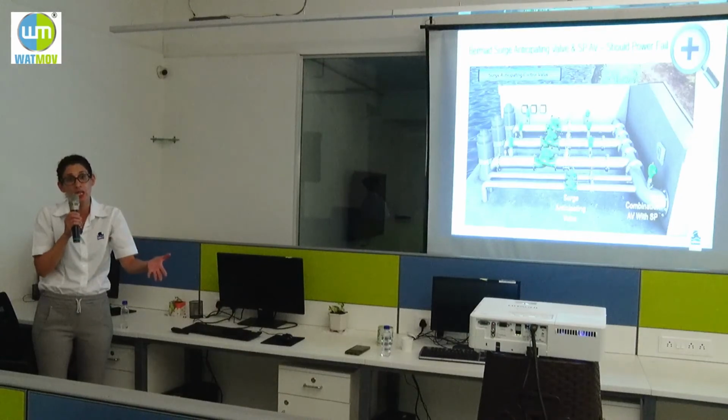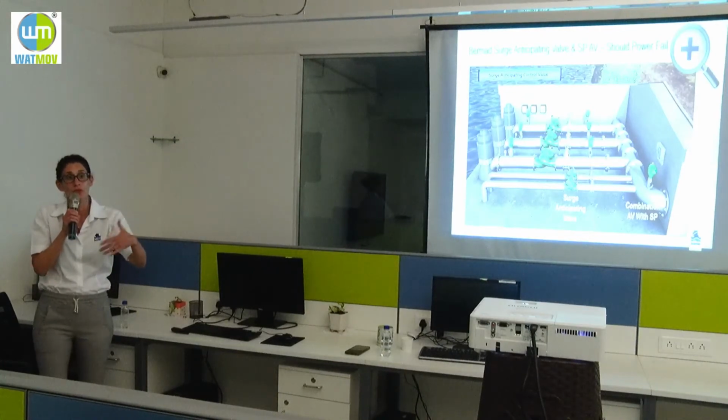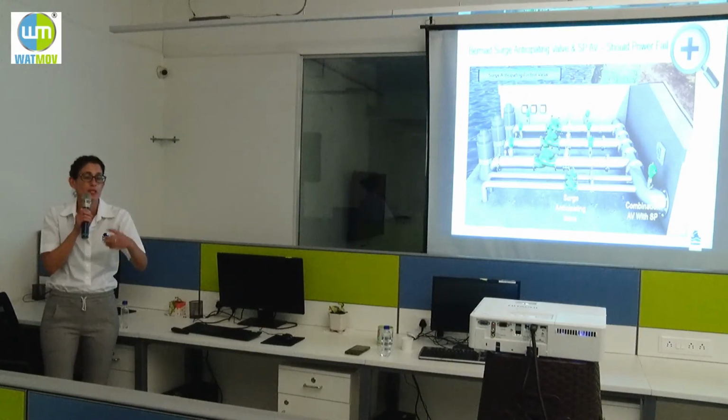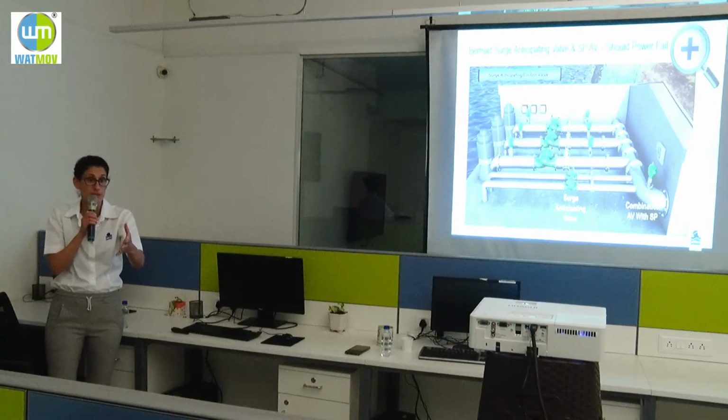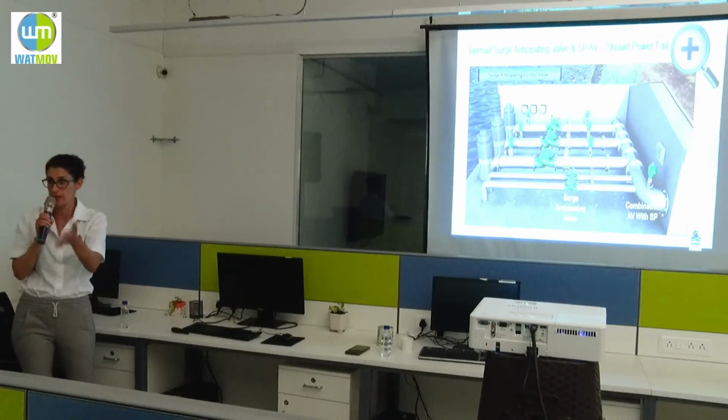Anyhow, in irrigation, you install air valves because you fill up and drain the line all the time, and you need, during pressurized operation as well, to expel the air bubbles, because they will harm the accuracy of the water meter, sensors, etc.